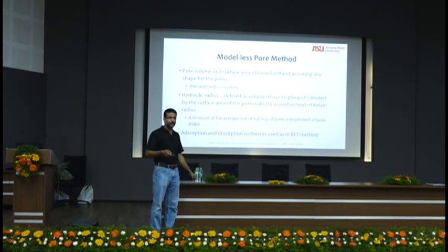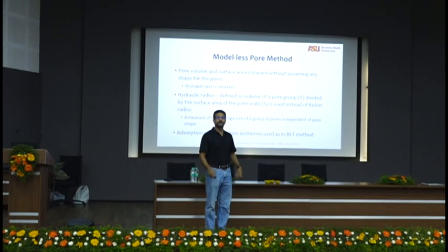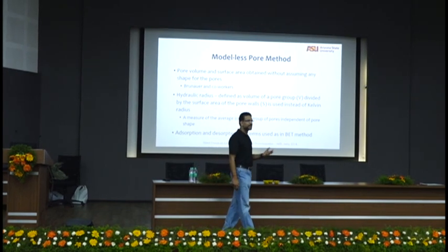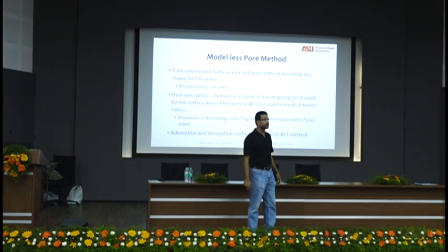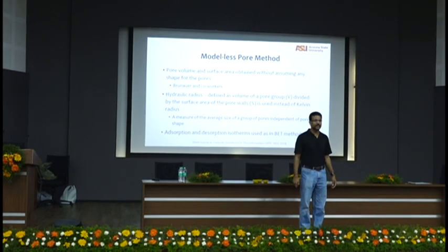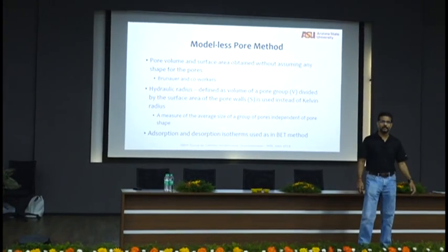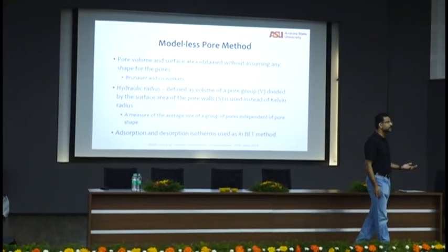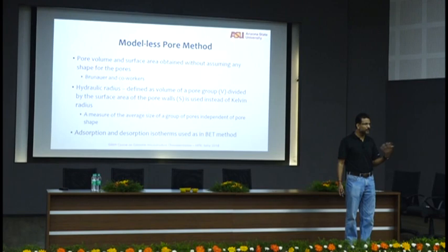They're random shapes. But by the same argument, you can ask me, who told you the cement particles are spherical? If you look at any computer model, they'll consider cement particles to be spherical. The sphere is the size that we can computationally handle. Angular particles become extremely expensive computationally. If I have to engage a supercomputer for 6 days to find out the hydration of 1 cubic centimeter of cement, it's not worth it. These models have to be run faster if I have to make realistic calculations, and if more people have to use them. If you give very complicated models, nobody will use them. That's why we need to simplify.